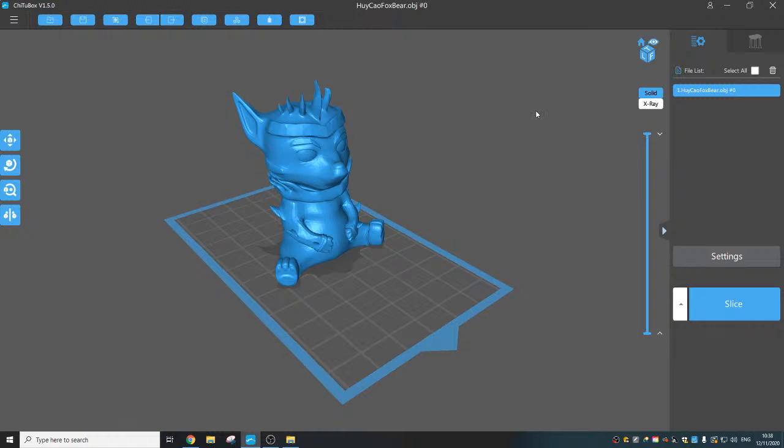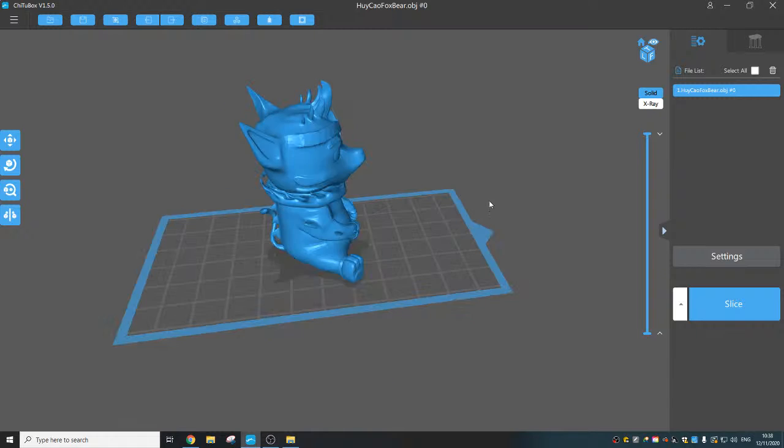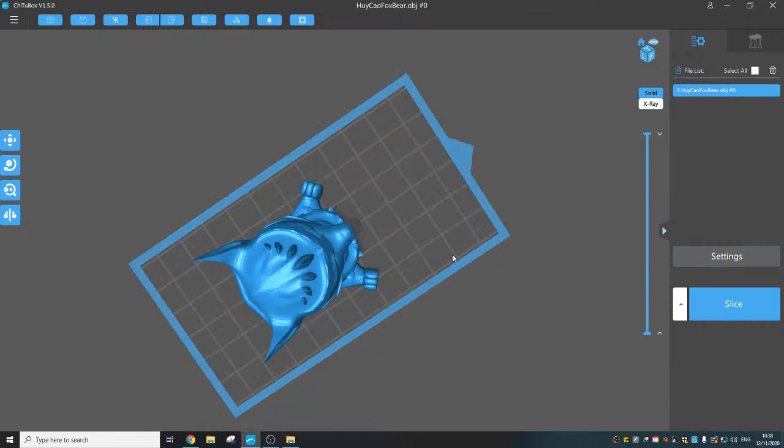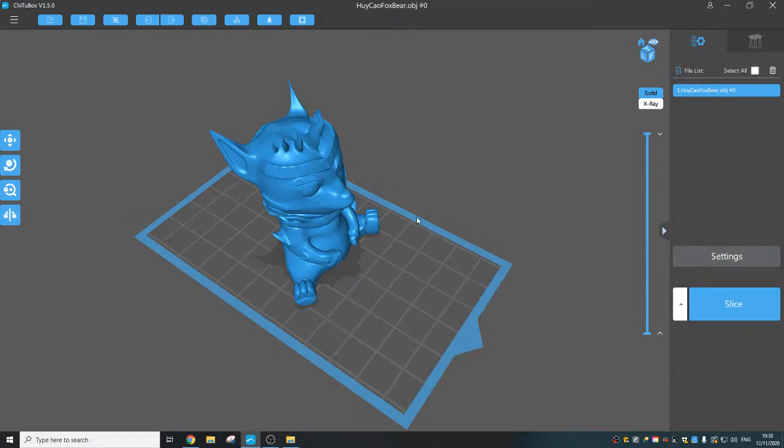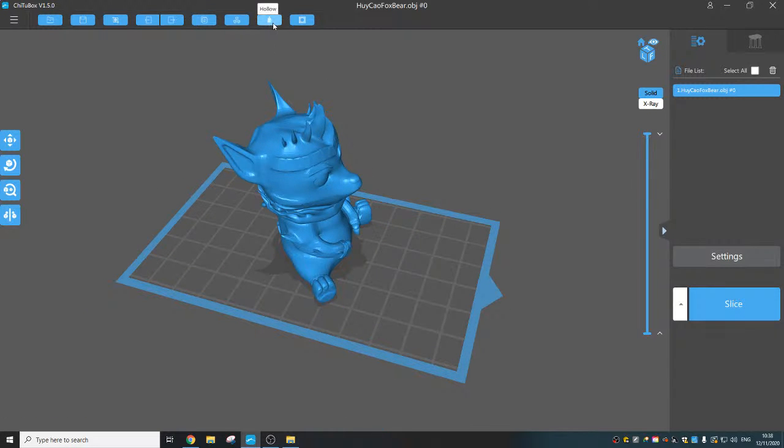Okay, the next thing we need to do is actually, let me hollow out the model now. I wouldn't want this model to be a complete solid because of the size we're going. It will take long to dry on the inside using UV lights. So I'm going to state that I want this to be hollow. So I'm going to go to hollow mode, and then I'm going to say I want the thickness to remain on 2.